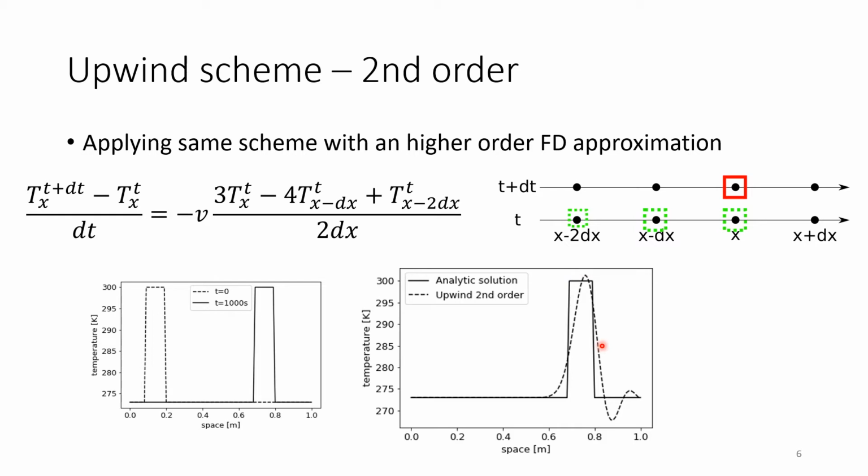You might say, well, okay, that's better than first order. What is it? We are overshooting. We are violating boundedness, right? The peak is now a bit far to the right. And we still get that kind of bell-shaped behavior, though much narrower now. So we reduced maybe numerical diffusion a bit. But again, we violate boundedness.